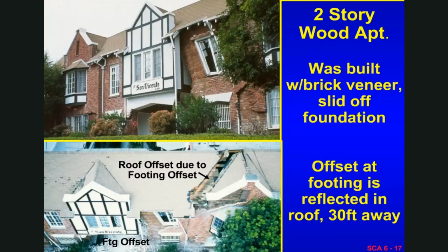Here's some examples. Actually, it's the same example of a two-story apartment house with brick facing. The most important thing here, the important hazard, is the brick veneer that can kill us if it falls off in an aftershock. A large amount of it has already fallen off. And in this particular structure, there was a side of it that didn't have any veneer, so obviously that would be the side that we would enter from if there were any victims.